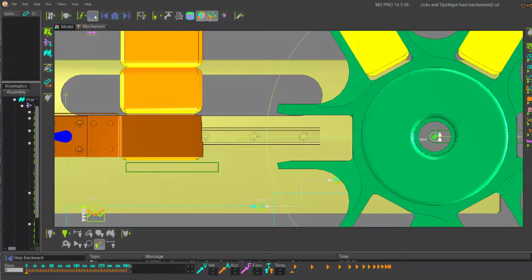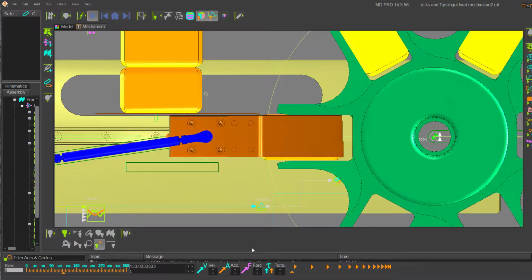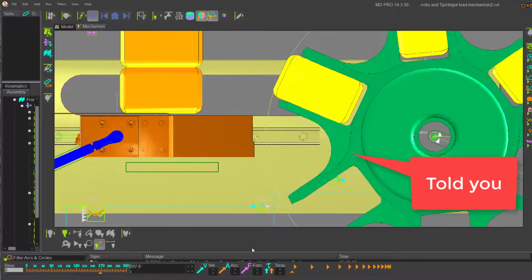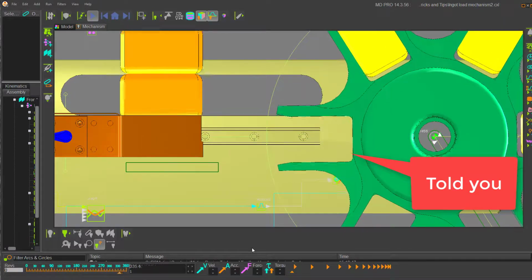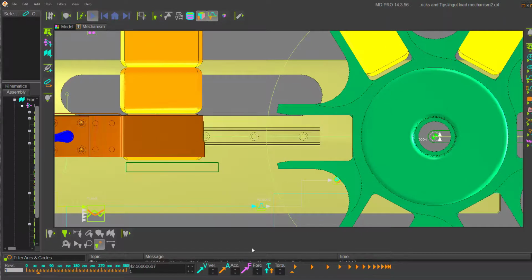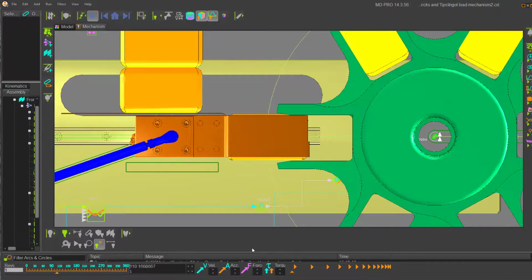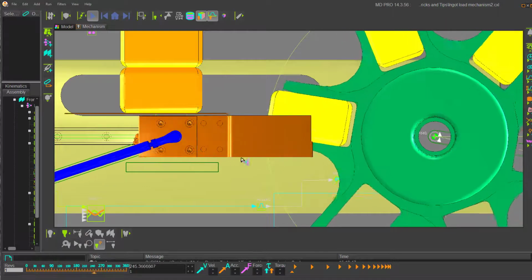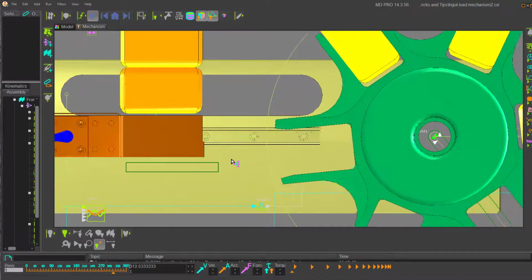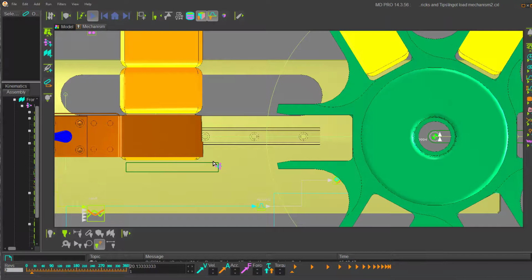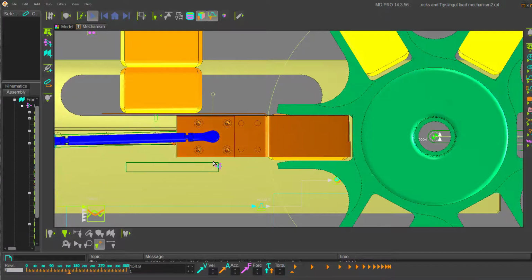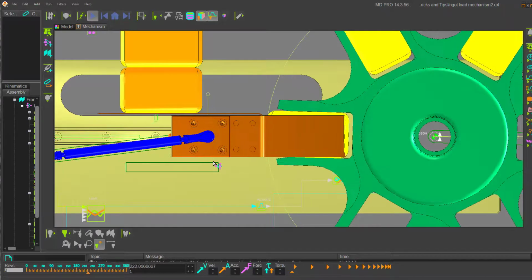So we can now cycle the machine with this radical new pusher motion and see what the implications are. Now we'll see straight away that the retraction is happening much too early. However, the push is fine. It doesn't seem to be causing too many problems, the insertion. It's just the fouling of the ingot on the retraction. So what have we got to do? Well, we used to have a dwell in the motion, but maybe we can use another trick to introduce a pseudo dwell.